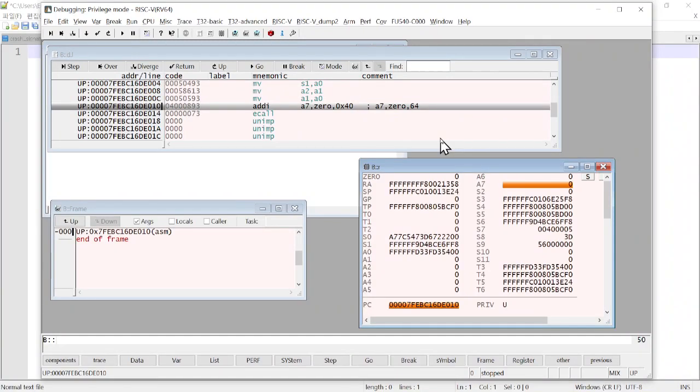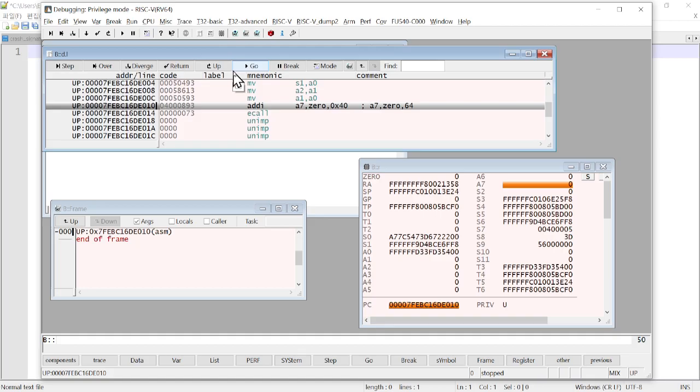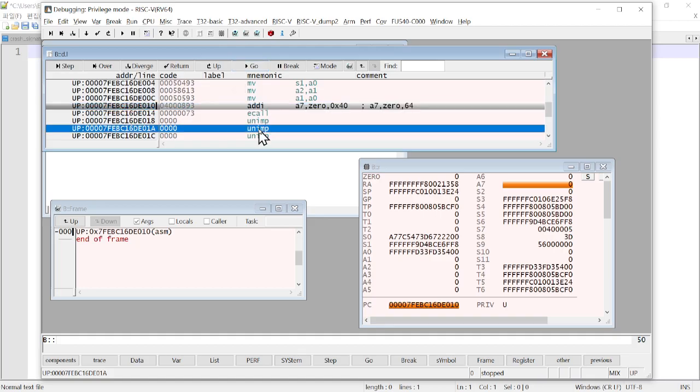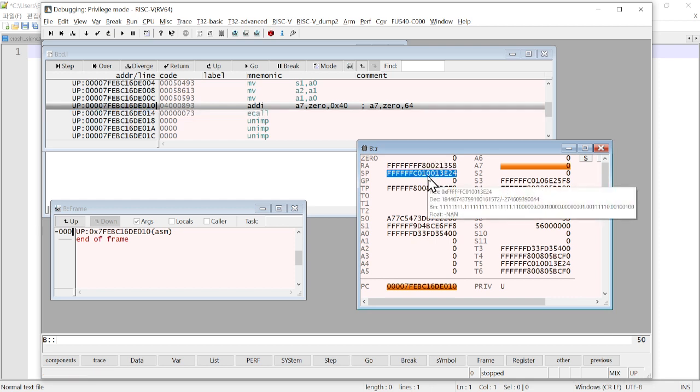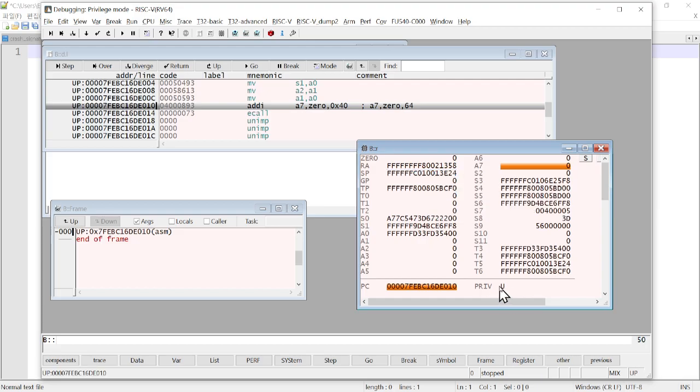Now it is the debugging time. So what we are going to do is to perform an interesting debugging practice to see the previous privilege mode. What you are looking at is the TRACE32 debugging program, and this is the instruction window with the address and then assembly instruction. This is the register window in the RISC-V architecture. As you can see, the set of general purpose registers are displayed. And here is interesting information that indicates the current privilege mode.